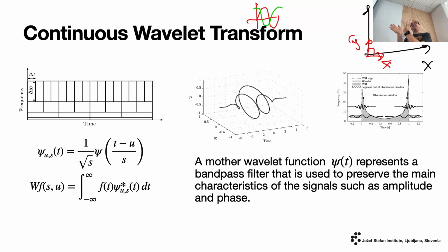I cannot explain it this simply, but you have to trust me that these wavelets are really such functions that generate such an orthogonal space. And why is this orthogonality important? This means that we can separate a signal in time and frequency in such a way that if we sum it up, we get the whole signal. Nothing is doubled, nothing is lost.